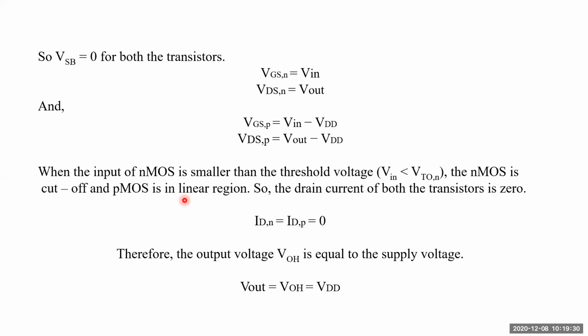See now here, whenever the NMOS is off, then definitely the PMOS will be on. Whenever the PMOS is on, what happens? The VDD will flow through the channel, and that VDD will be stored in the output capacitance. That's why we say that our output is obtained. That output is nothing else but Vout equal to VDD.